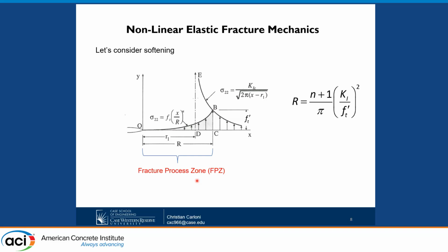Okay. So for example, to go back to the practice, concrete. If I have a concrete with small aggregate or a UHPC where they use fine aggregates, that softening is pretty small in size. But if you use large aggregates, okay, that softening is gigantic, okay?